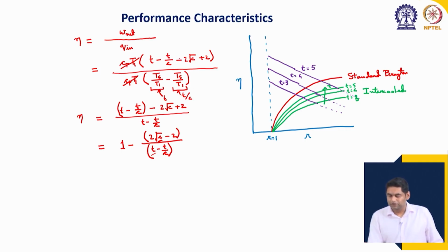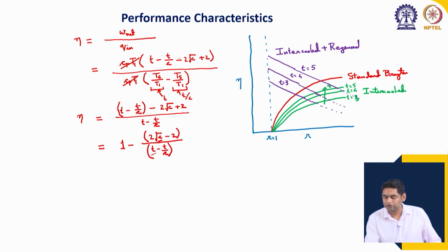So, these are the intercooled plus regeneration curves, and the nature is similar to normal regeneration, but because intercooling and regeneration together are very effective, the efficiency actually increases compared to the simple regeneration cycle.